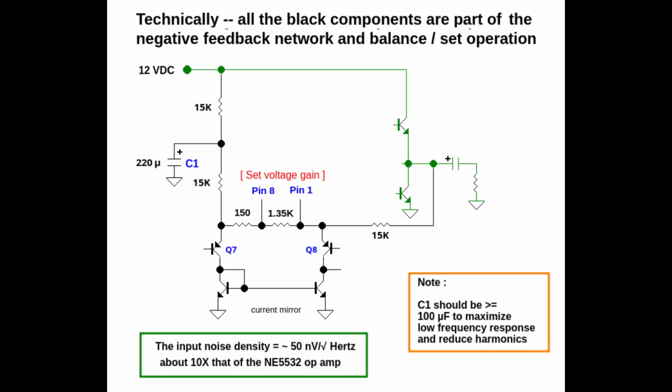It's feedback circuit time. All components colored black are part of the feedback circuit or help maintain proper operation as you change the voltage gain, and to a point if you add additional negative feedback to shape frequency response by placing an external RC network between output pin 5 and pin 1.